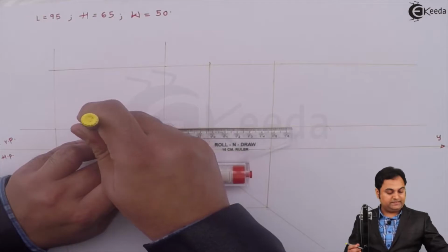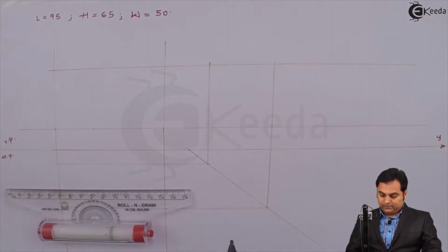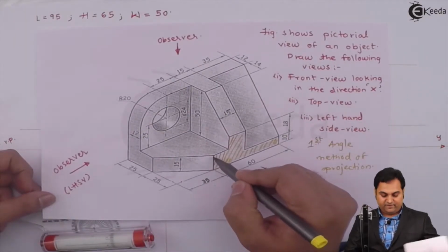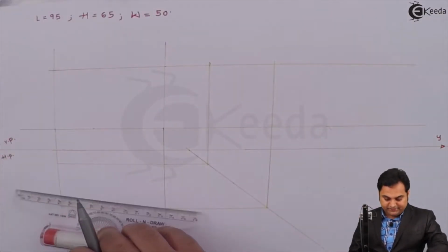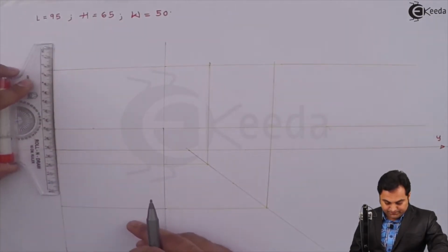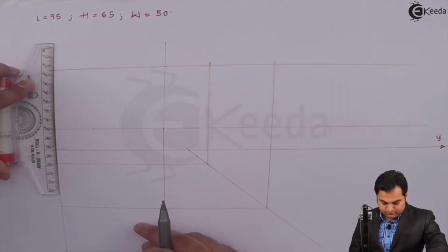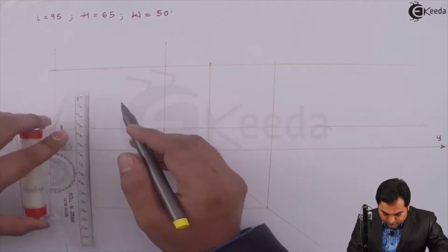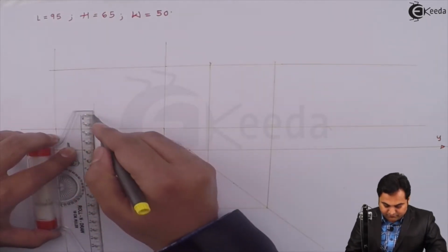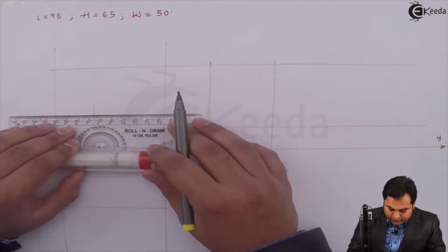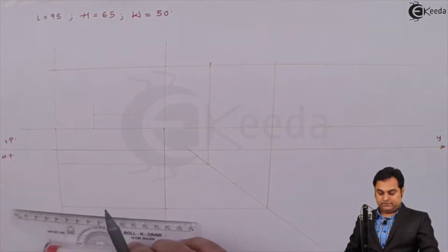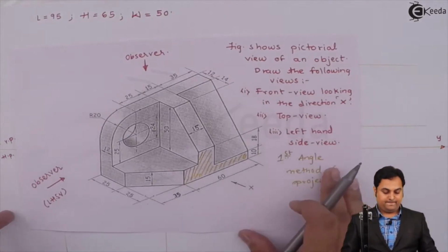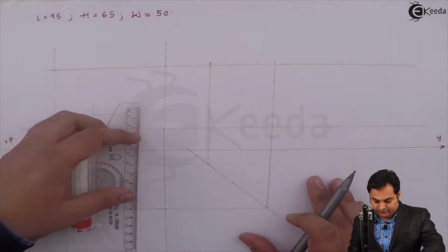Into the front view. Next, after taking 60, here it is having a height of 15 mm. So projecting it with the help of light vertical line. Measuring 15 mm. Drawing a light horizontal line. After that, it is of 10 mm height from the other side. So measuring 10 mm height from the right hand side.